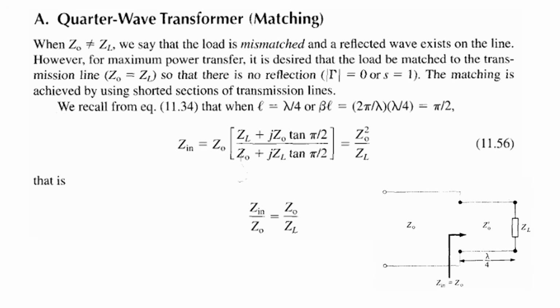Here we are going to use a component of the transmission line for matching. For this technique we are adding it in series. So here you can see this is your transmission line, and this is the component that we are going to add in series along with this transmission line. Because of the addition of this quarter wave transformer, the impedance will be matched, that is now we will receive Z0 equal to ZL. So how can we achieve it? You can check here.